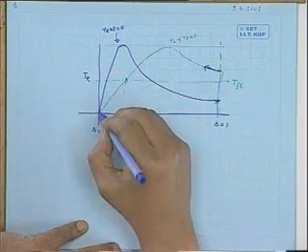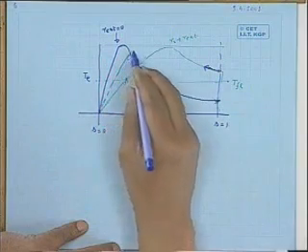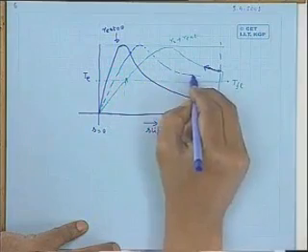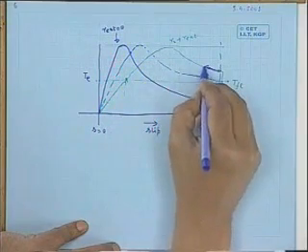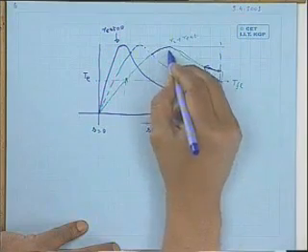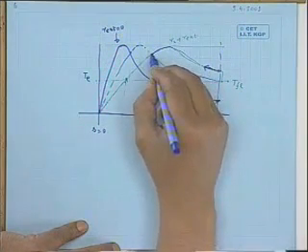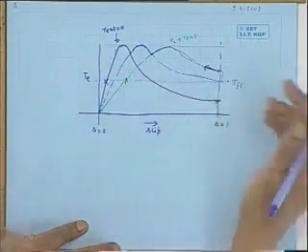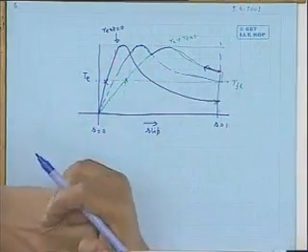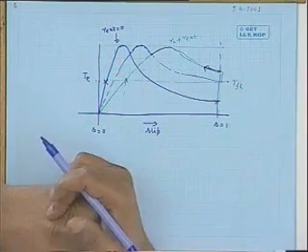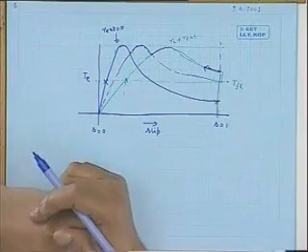Okay, now what do you do? You cut out that resistance further. Suppose this is another torque slip curve. So it moves like this. It comes here. Suppose at this point you switch over to this curve, then it will go there, come there, and ultimately here, when all external resistance is shorted. Are you getting it?